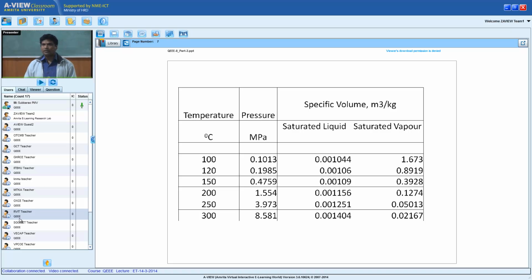If you go to the steam tables, you will see that with respect to water, this all corresponds to saturated liquid water and saturated vapor. Suppose I take 1 kg of water in a vessel and supply heat such that all the liquid becomes vapor. If the pressure is 1 bar, at 100 degrees centigrade there will be no temperature rise, but the volume rises. Imagine waiting for the entire mass of water, from liquid to vapor.